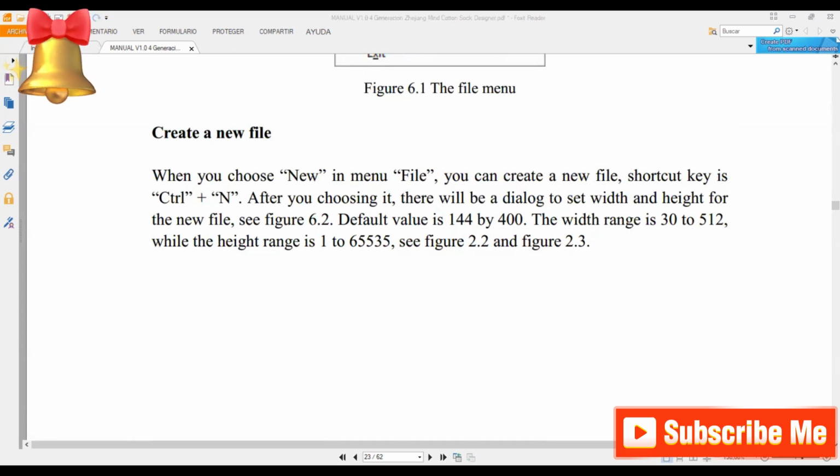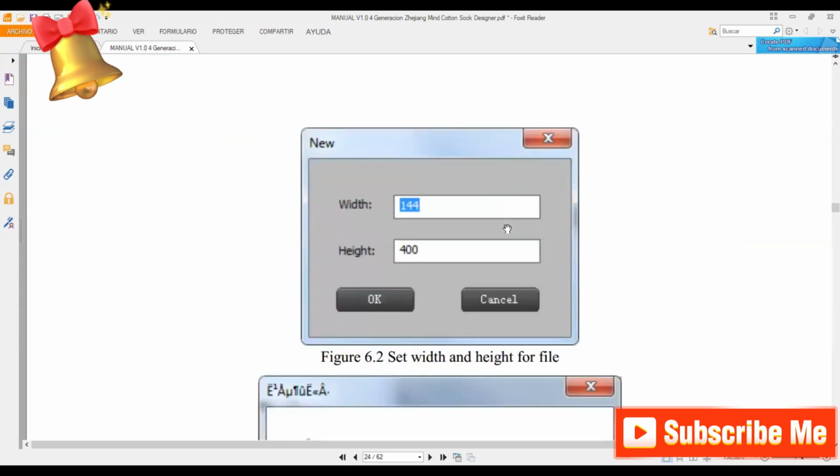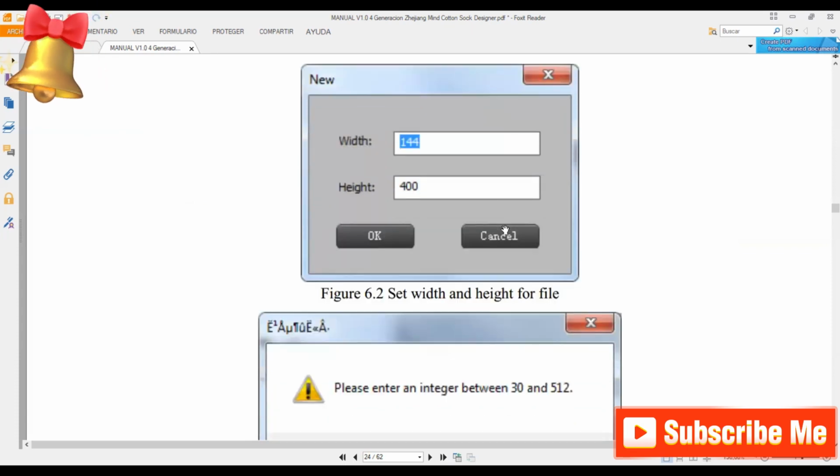Create a new file. When you choose New in menu File, you can create a new file. Shortcut key is Ctrl+N. After you choose it, there will be a dialog to set width and height for the new file. See Figure 6.2. Default value is 144 by 400. The width range is 30 to 512, while the height range is 1 to 65535. See Figure 6.3 and Figure 6.4.